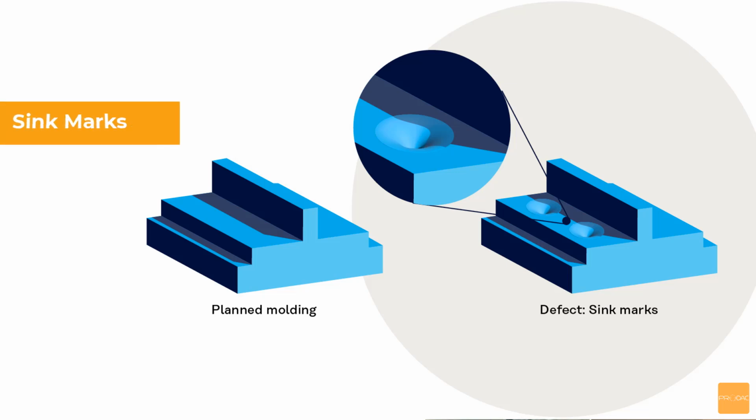The second defect is known as sink marks. This is a very major defect we come across during our molding. The designer also has to take care of his design to overcome this. It is not only from mold design, it also occurs from part design as well. So we need to avoid thick sections in our design. At any plastic cross section, we should not have a thicker section. Wherever you have a thick section, it will cause sink marks. So thick sections you should avoid.